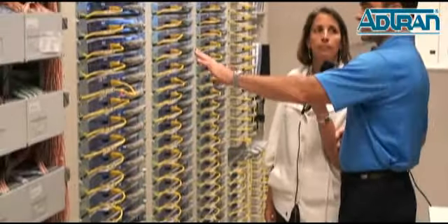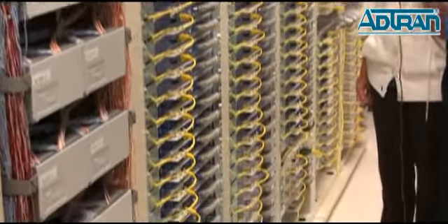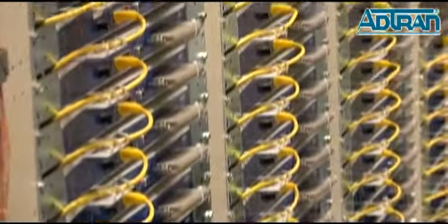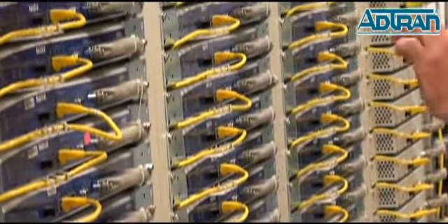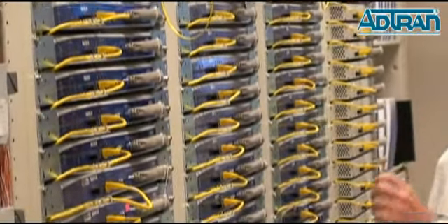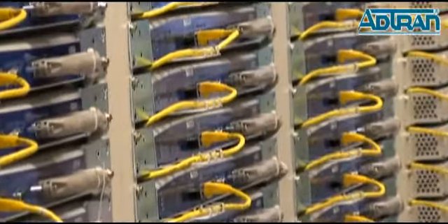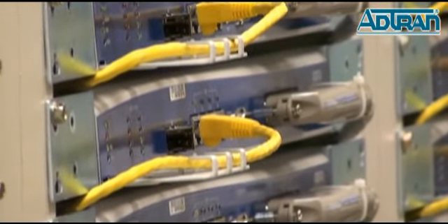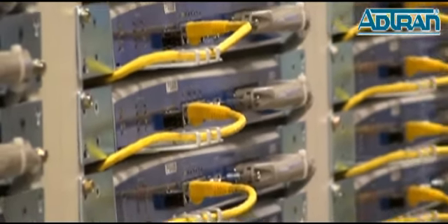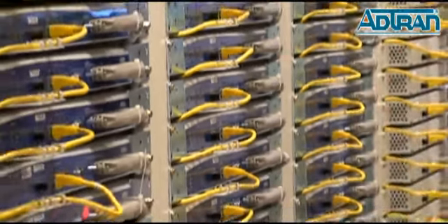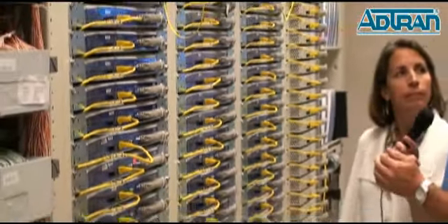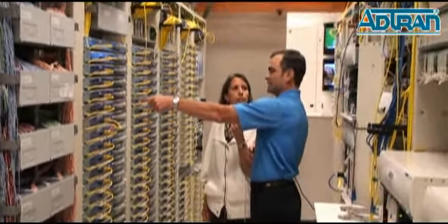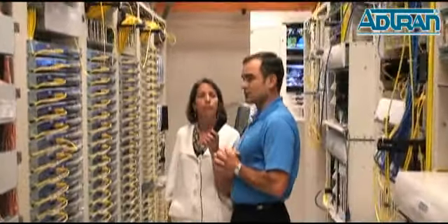So these are all what we call NCTEs. So these are T1 versions. We have HDSL versions, SHDSL versions right here. What this allows a service provider to do is bond a certain type of copper into an Ethernet service delivery to a customer. So these would go at the customer sites. But the great thing about this solution is that as a customer's business grows, they can call the service provider and simply request another 1.5 meg. And then the service provider can bond any loop to any other loop out of our shelf and supply them with an additional 1.5 meg. Without a truck roll, you mean? Without a truck roll. So it's a great solution for us.